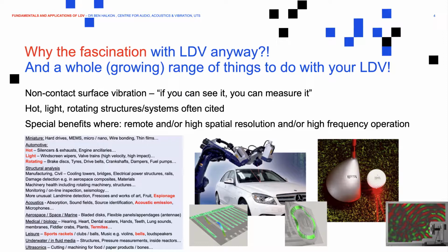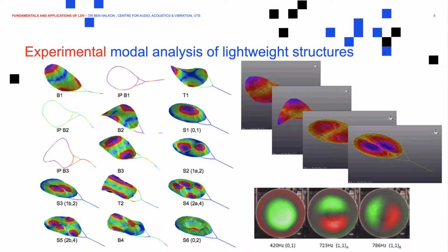These instruments are clearly highly sensitive devices, but industrially viable and robust. So we can make measurements from sports balls and pieces of sports equipment, and indeed from things that we're all very familiar with. And the automotive industry has really driven the development of these solutions. They will all have scanning vibrometers with at least one dimension, if not 3 dimensions. So there are 3 heads here organised around some sort of a triangle or the vertex of a cylinder, and we can make 3-dimensional non-contact vibration measurements across this entire structure.